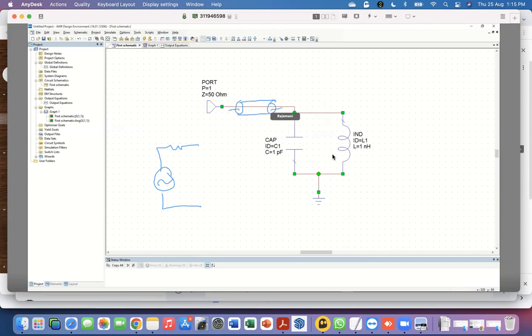Some finite transmission line, which is again 50 ohms characteristic impedance. And this launches a wave, and that wave goes like this. So, there's some wave here. It goes like this. It reaches this point. And this, of course, is not a 50 ohm resistor to ground. So it's going to reflect backwards.